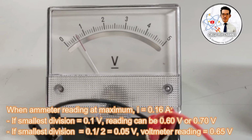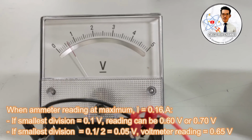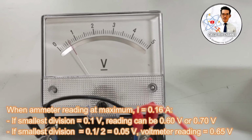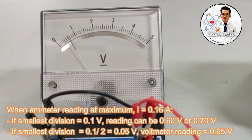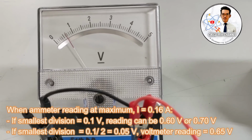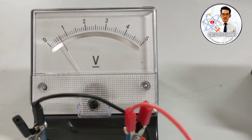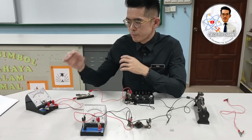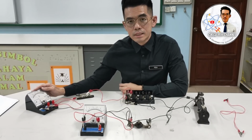So one segment represents 0.1. So here you can define it as 0.6 if you are using the bottom segment. If you are using the above segment, there will be 0.7. Or you can choose the middle, where the smallest division is 0.05. So the reading here can be given as 0.65 volt.